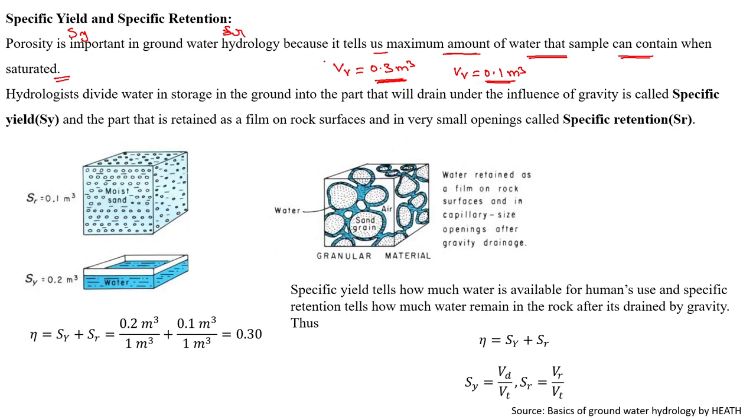Okay, this is very important to us because in irrigation we often need to saturate the soil. Suppose we supply water to the field when the plants are reaching the permanent wilting point; we need to supply water such that the soil becomes saturated. In that case, we should know how much water to supply for the soil to become saturated.